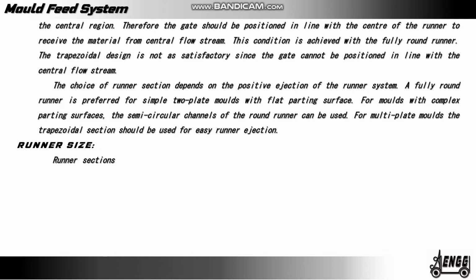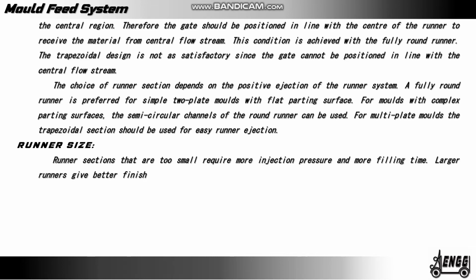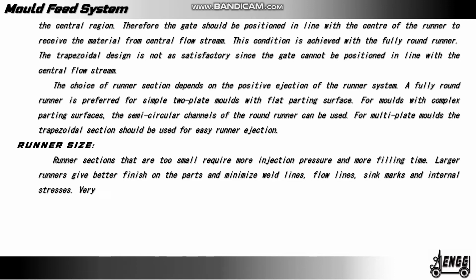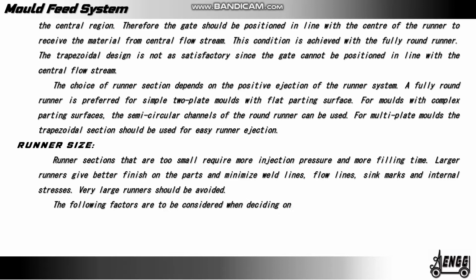Runner size. Runner sections that are too small require more injection pressure and more filling time. A larger runner gives a better finish on the parts and minimizes weld lines, flow lines, sink marks and internal stresses. Very large runners should be avoided. The following factors are to be considered when deciding on the runner size.